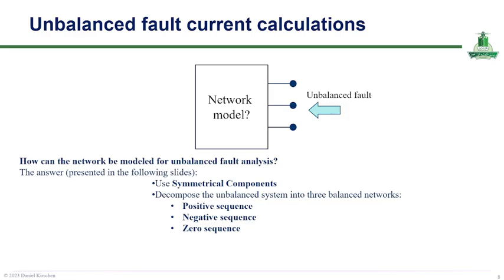This technique transforms the original unbalanced three-phase system into three separate balanced networks. So we can use this concept here, including the positive sequence, negative sequence, and zero sequence components.